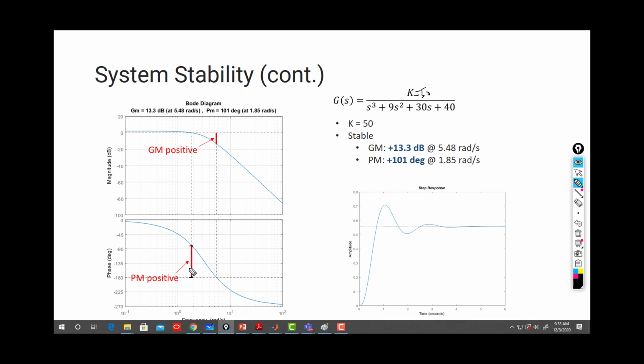right? If it is positive, and if the gain margin also is positive, that means the system is stable. Let's find the gain margin. How to find it? We find the gain margin by looking at minus 180, and going up to where it crosses the Bode plot, and we go up to 0. And this is my gain margin.